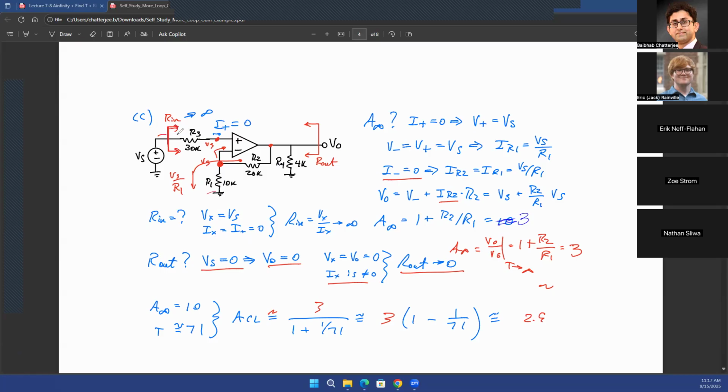Of course, as you look here, as you look into this particular direction towards the right at the input node, this is a negative feedback circuit. That means virtual ground property will hold. However, note that this point's voltage is Vs. This point's voltage is also Vs, right? So even though you have a virtual ground property, the value is not actually equal to AC ground. The virtual ground property is there, but you do not have an AC ground at the non-inverting terminal of the op amp, right?